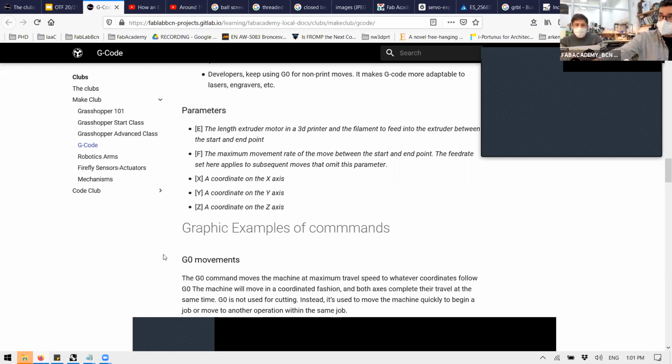In industrial environments, you mostly program the code automatically. If it's a repetitive task, they do it manually to make it optimized, with massive control on the way it's done. Exactly. So for example, in your case, the CNC job you made with RhinoCam. RhinoCam is a processor that produces the code for your machine. In the CNC you have seen the code displayed. Why? Because if something bad happens, you know exactly where to stop, or you can introduce commands.